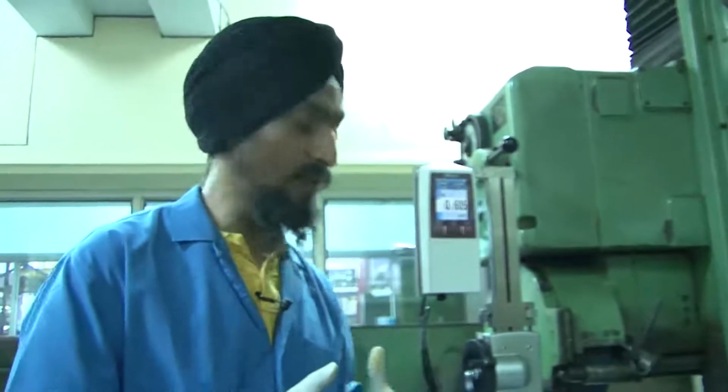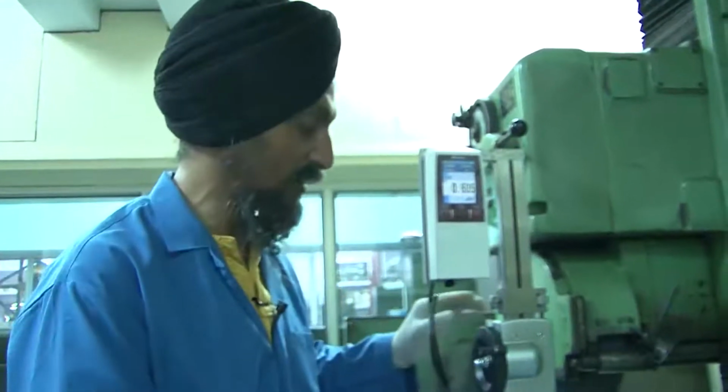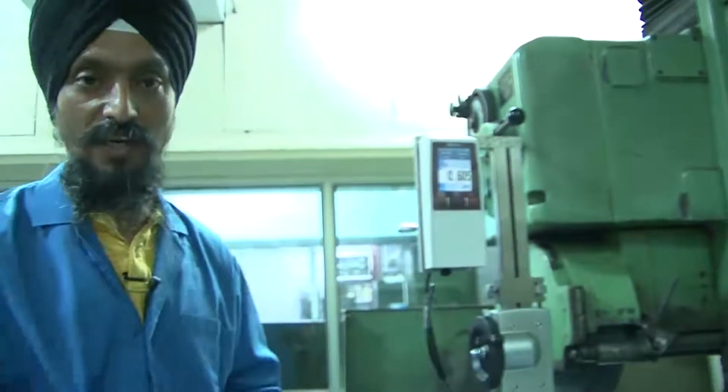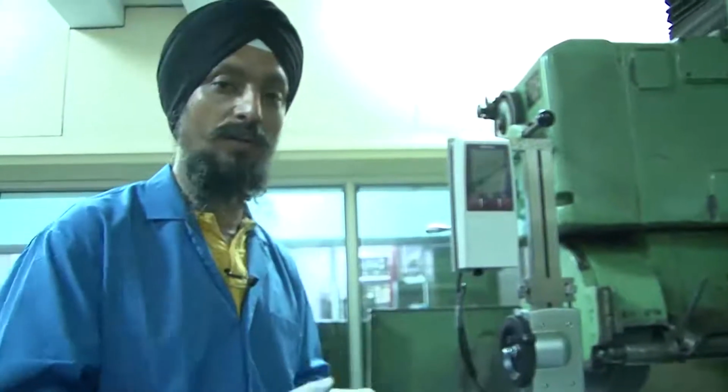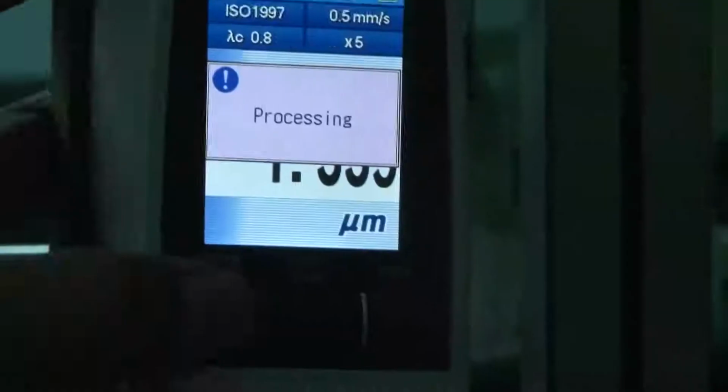In different machining treatments, that is different depth of cut and speed combinations, we might observe different Ra values and different force values as well. Those would be used to finalize our setup, which gives the best mix of these two.